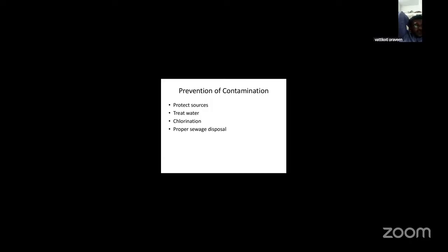What is the biological analysis of water? Biological analysis of water is the determination of the microbial quality of the water. It helps to detect contamination by human and animal fecal matter, which means the water may carry disease-causing organisms. Instead of testing for every pathogen, indicator organisms are used, and these bacteria indicate the presence and type of contamination.